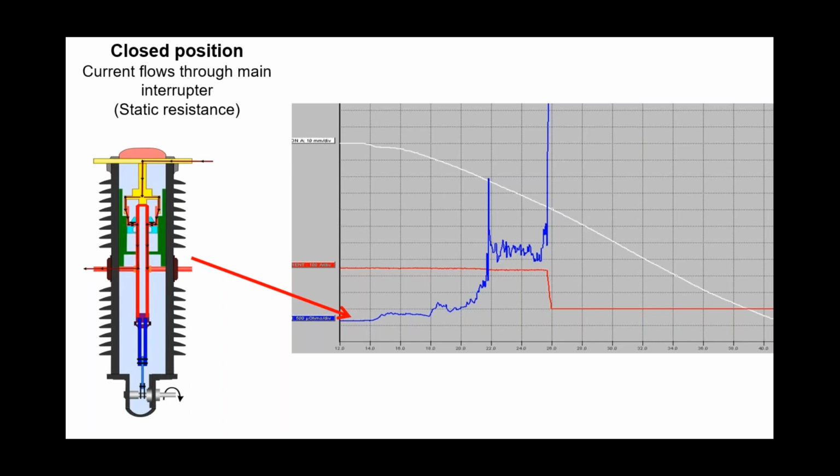But materials with very low contact resistance will not be very good to deal with an arc during normal operations, opening, closing, or opening during short circuit currents. Hence, you have a second contact called the arcing contact, which is designed to sacrifice itself whilst opening or closing. So whether you want it or not, that arcing contact will wear slowly, and hence you need to monitor that level of wear.